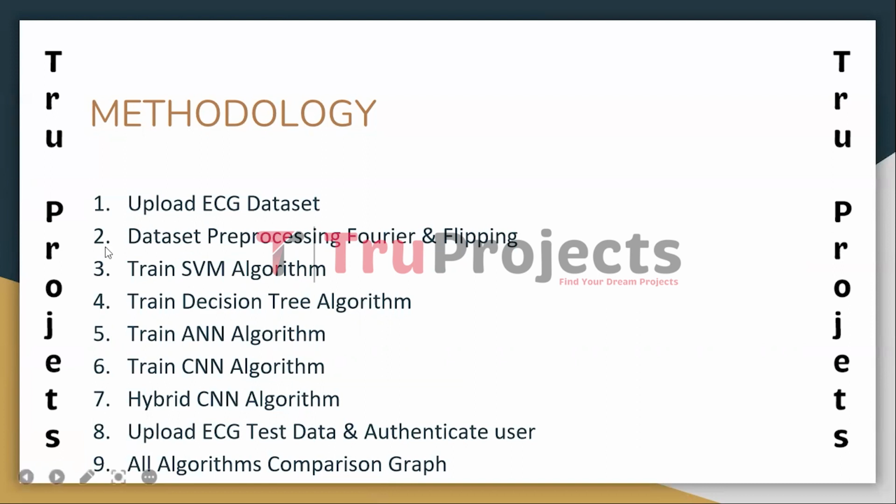And the second module is Dataset Pre-processing, Fourier and Flipping. This module focuses on pre-processing the ECG dataset. It involves handling the missing values in the dataset and applying the flipping and Fourier transform algorithm to extract the relevant features from the ECG signal. The flipping process helps to normalize the orientation of the ECG waveform, while the Fourier transform identifies the important frequency components.